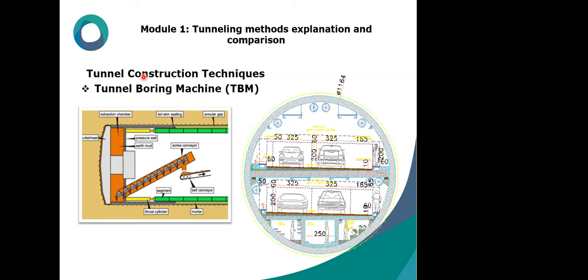For large span tunnels, failure mechanisms are highly probable, and using a TBM seems rational in those cases. This method is also applicable in frozen soils, weak or saturated soils. It has considerably faster progress in comparison with the NATM method, and usually it is more economical for long tunnels with uniform sections. I emphasize long tunnels with uniform sections.